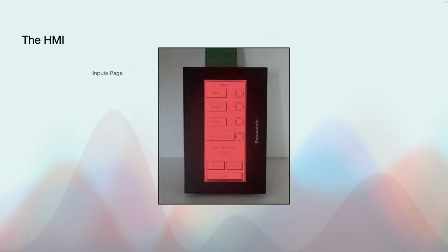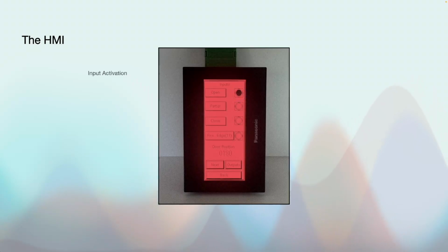The round lamps on the right side are indicators that the PLC is receiving an input. This allows you to monitor whether or not the operator is receiving an input from an activation plate or sensor without having to remove the cover of the operator and check the PLC itself. For example, if the operator is being given a signal to open via an activation input, the round lamp next to the open will darken.